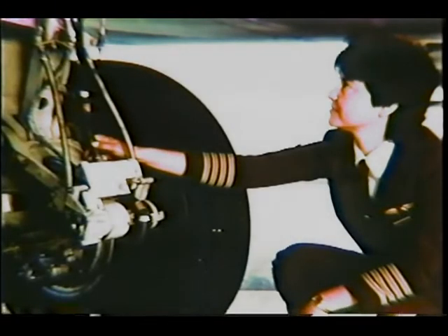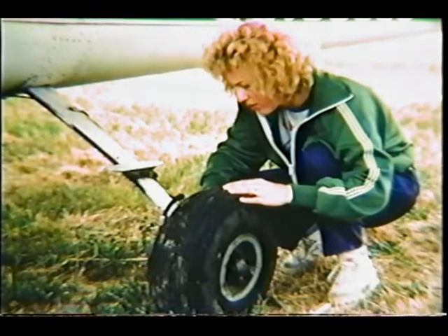Airline flight crews routinely inspect the condition of their tires prior to each flight. It's also a good practice for your personal airline. And don't just check the tires for depth of tread and proper inflation. Also inspect for bald spots, cuts, dry rot, and so forth. You know, it's amazing how many blowouts and other tire problems can be traced back to an inadequate pre-flight.